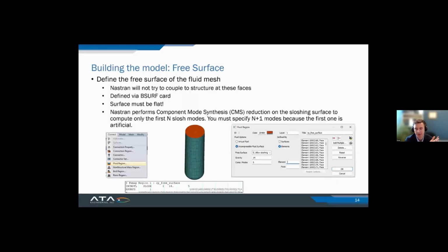That's the state of our advancement on that. We've had this discussion on if there's a way to kind of cheat your way around it to get more Hydra-like. Ken, feel free to jump in there if you've done anything separately. Currently you can't have the fluid nodes in the B set of a super element. That's not allowed. So you can't just try to make a super element of the fluid directly. Like Mark said, we've discussed some tricks to try to get around this, but we haven't made any progress, and certainly nothing that we can competently say will work.